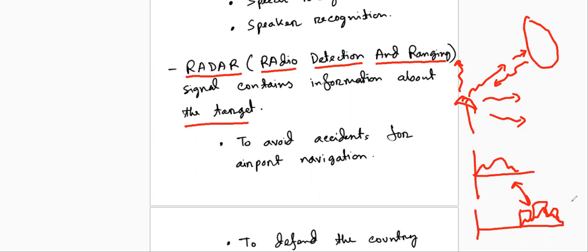It might happen that if the object is an aeroplane, it can also send some signal. So if it is an unknown signal, you can also find it by the correlation. So the correlation gives you two things. Number one, whether this is your own signal, and instantly it will also be checked, if that is your own signal, what the distance is and how far the object is.